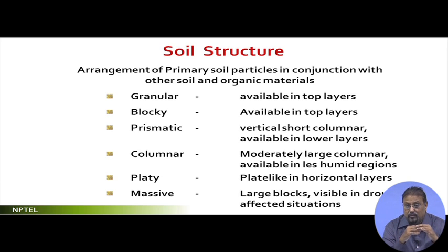When it is wet, in the normal situation when there is more water within it, if you plan for something, maybe at some other time when there is a depletion of water, it cracks. So this expansion and contraction of this particular soil makes it structurally very unstable. Structurally means soil structurally unstable. I am not talking about the building material structure, I am talking about the soil being structurally unstable.